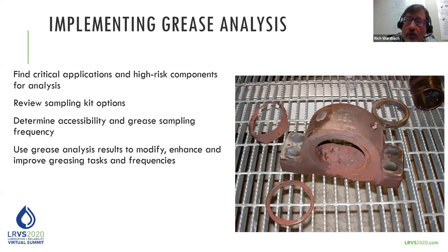And one thing about grease that's different than oil: with oil, we always say get to the machine while it's running and take the sample, or sample it just after it shuts down, while all of the particulate, especially the wear particles, are in suspension, and we get them in the sample. Well, when we shut down a grease lubricated piece of machinery, there's no settling. So that same sense of urgency is not there to rush right in and get the sample, or even to get the sample while the machine is running.